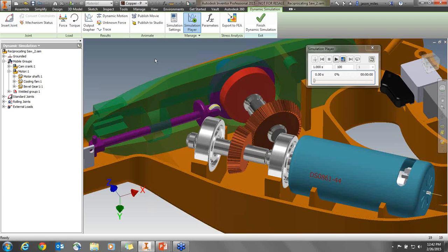This simplifies the model for simulation purposes. If you want to retain the lug nut's rotational degrees of freedom, you can do so using the retain degrees of freedom command. The same is true in reverse: you can use ignore degrees of freedom to restrict the degrees of freedom of a component. So to ensure that the follower roller contacts the cam while also keeping its degrees of freedom, we're going to have to do a couple things here.